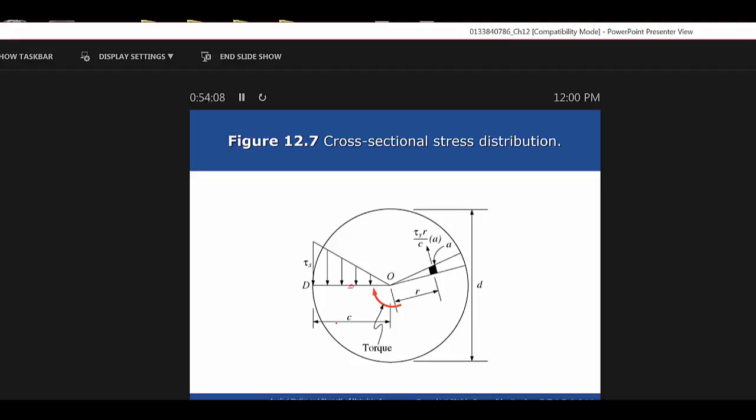And that's what it said, remember, that relationship between the stress... Let me go back to my notes now. Develop the relationship between the torsional shear stress, the torque, and the material physical properties. So that's where these calculations are going to pay off for us. To find the max resisting torque, or the allowable torque, we can rearrange that again. Note that is equation 12.3. The last equation, to find the shear stress if you know those others, is 12.2.